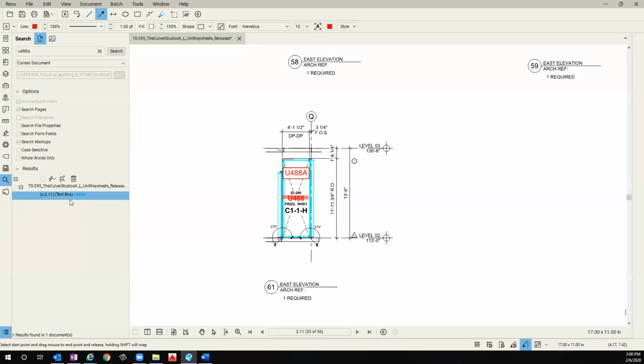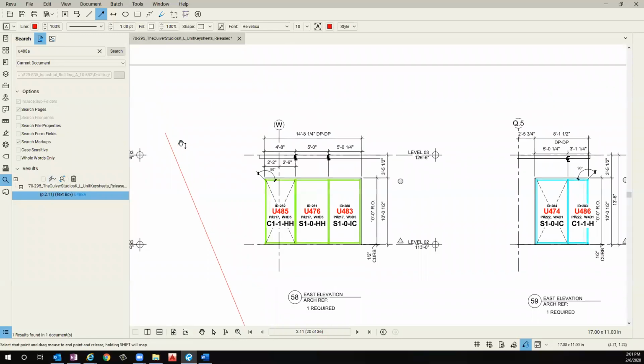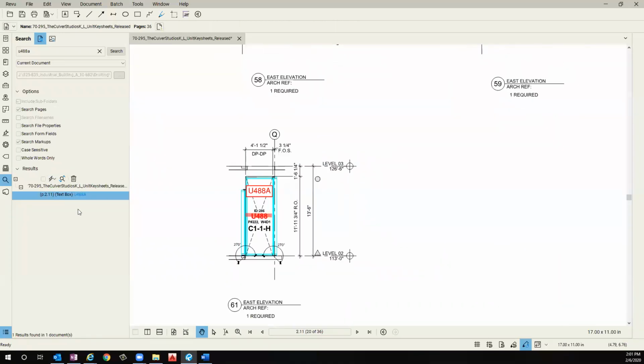This is just going to show up as a text box, so this doesn't give me the opportunity to do this highlight checked on it. So let's say we check this as an updated mark number, and we agree that the unit 488 that we checked is actually correct. Then, since we can't use that highlight checked, we'll line through it, and then we'll just change our line color to yellow. So the visual will look similar. We'll be able to tell that I verified that this updated unit mark number, marked 488A, is actually correct.